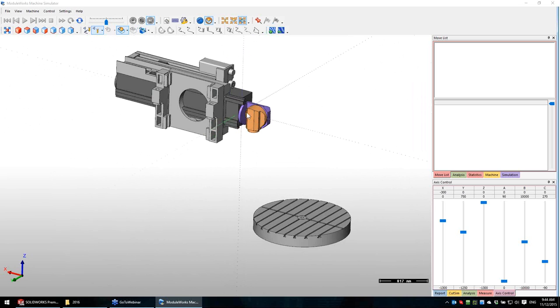The next option is I can work 5 axes simultaneous on this machine with different axes. When we work 5 axes, we select 3 linear axes. We can control in operation 3 linear axes and 2 rotary axes. Now, if I create several submachines, I can select on one submachine, use A and C axis on the head, A and the rotary on C. So I will work in kinematic head.